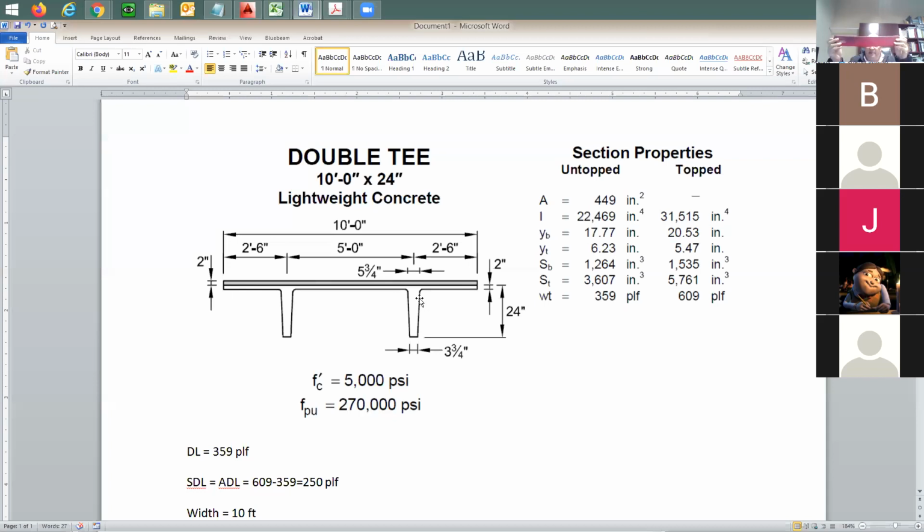Okay, here's the double T. It's going to be this piece here. I put the pre-stressing force already in there. Okay, start to camber. I move it to put it on the beams, on the side, on the construction site in the building. Then I'm going to put some concrete topping, right? Now, the axial force that I put here in the double T, these things are going to get transferred to the concrete topping, even though I casted this after the fact.